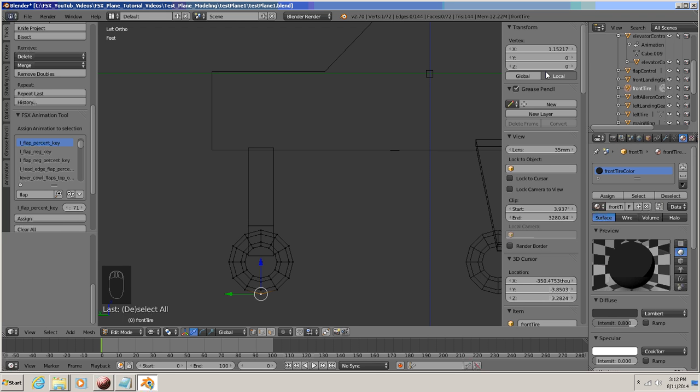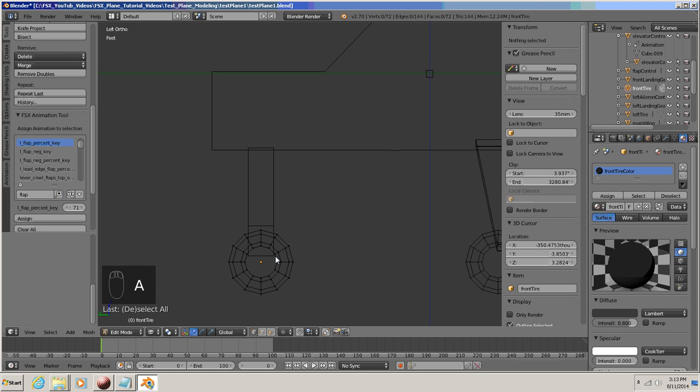We're then going to go up, and on your transform on vertex, we're going to click global. On the Z-axis, this is showing that our vertex there, which is at the bottom of the tire, is at a negative 7.94192 feet. So this is a very precise way to measure, much more than what I was doing. So thank you capt_x for that, and for the Blender2FSX add-on.